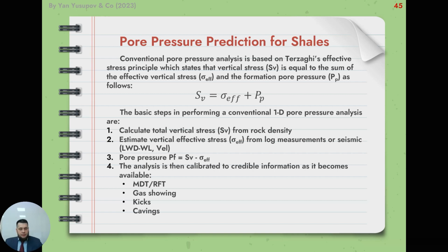Let's discuss pore pressure prediction basics for shales. When we talk about predictions of pore pressure, commonly we are speaking about only shales, because shales work with the Terzaghi effective stress principle, but sands don't.